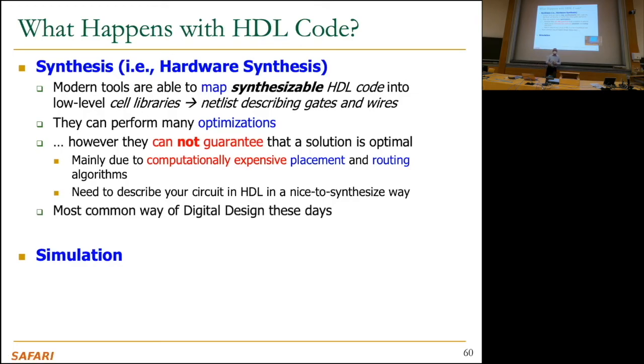Most of the time, you don't implement the circuits yourself. For example, you don't take a cell level library and put together different gates and modules that you find in it. You go through a tool that compiles your hardware description language into that cell level library. But if the resulting circuit that comes out of this tool is not good enough, and you have high requirements, for example, you want to design the fastest ALU in the world and the tool is not good enough, then you actually need to go and implement things by hand.